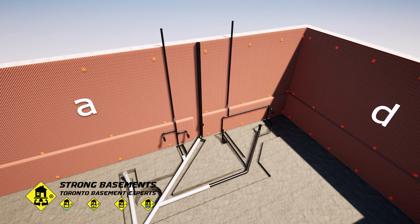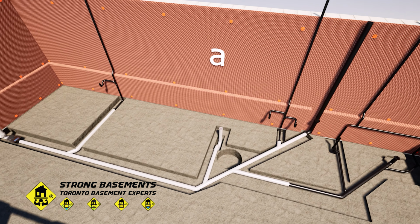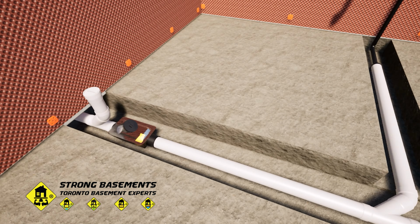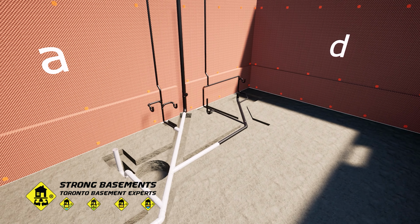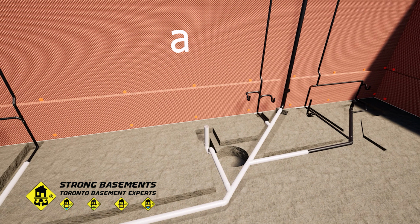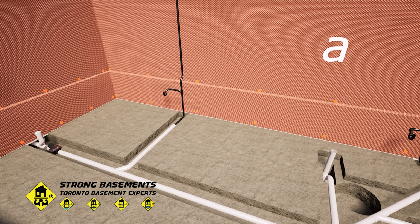This includes installing a new main drain line from the vertical stack to the exit point, a backwater valve to protect your home from sewage backup, and all the necessary plumbing rough-ins to prepare your basement for a future bathroom, laundry suite, or kitchen.